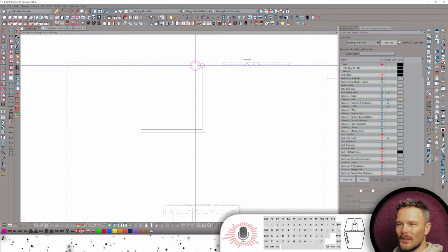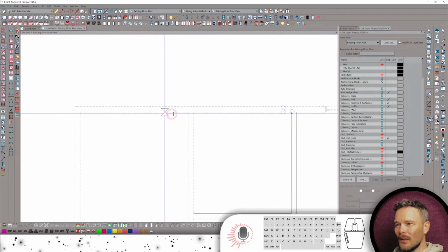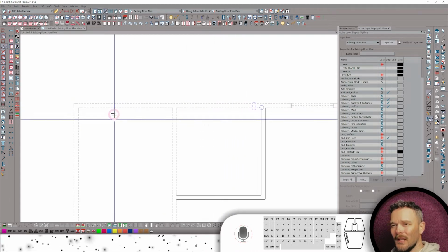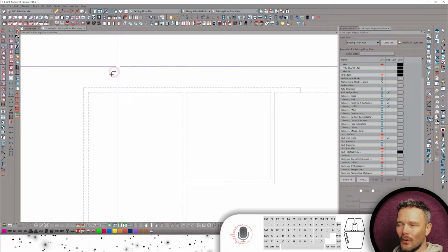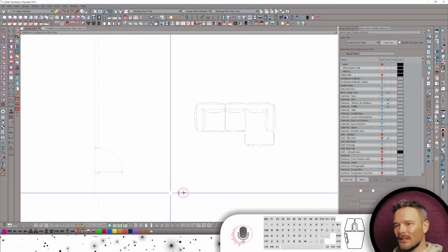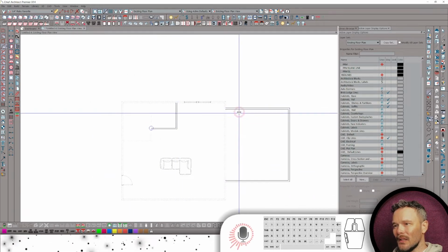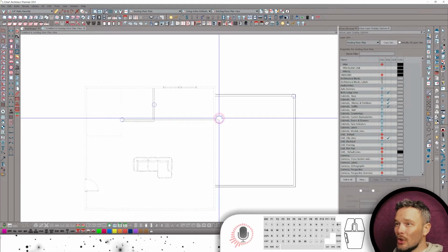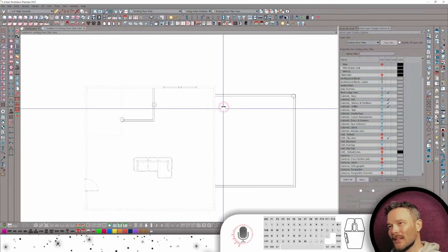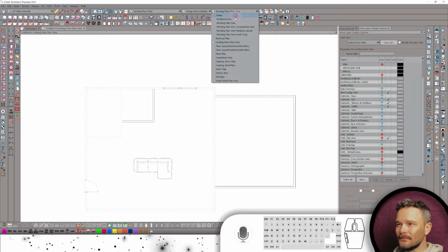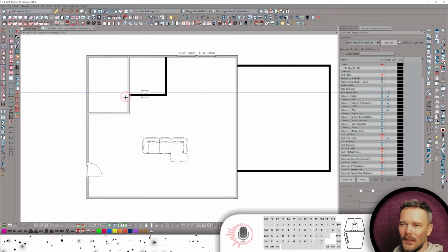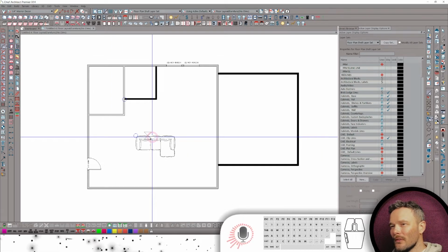This is just demonstrating what an underlaid existing plan will look like when you use it as a referenced plan to your floor plan, which is just showing you the existing floor plan layer set as a dashed line. You can see the difference between the new versus the existing here. I do not do my demo plans on the new plan. I do it on my existing plan. So I use two separate plan files, an existing plan and a new plan. Here's our floor layout, furniture, no dimensions. This is just going to show a floor overview with furniture.